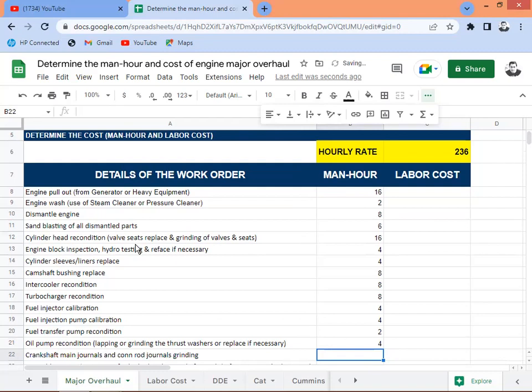Then for the crankshaft journals and connecting rod journals, you need to grind also, by using a sandpaper, a special sandpaper used for grinding. This is not a normal, standard sandpaper. They wrap a rope around it, and then they grind it using the rope. But I think you more or less already know how it's being done.